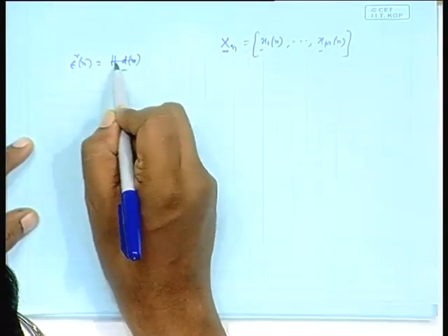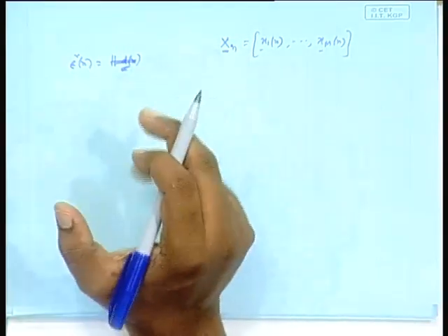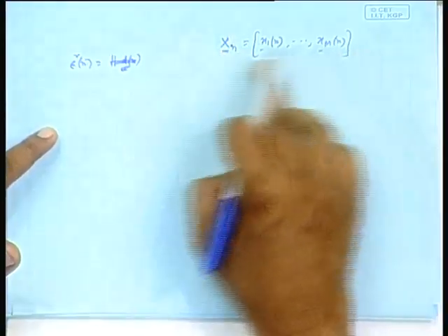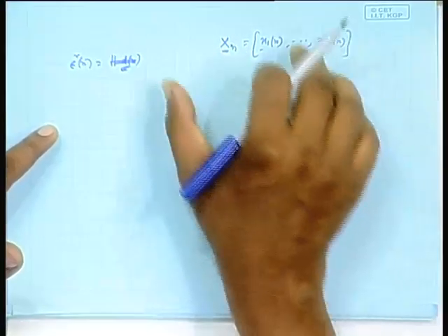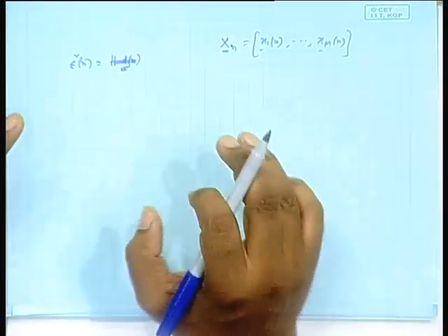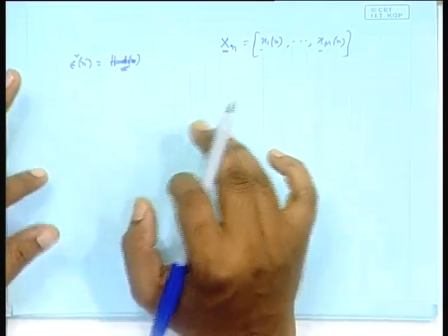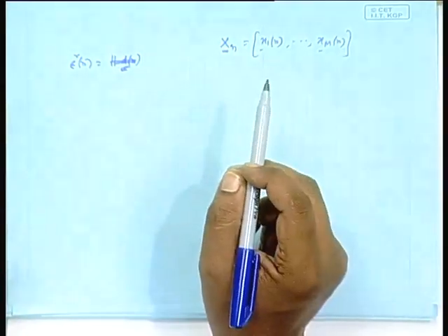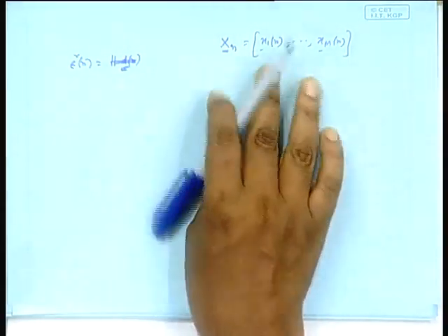This norm I converted into the conventional norm by writing out that delta part explicitly. Actually, you take d n minus x n into c n, that error vector, and take the norm square. In that norm square, your lambdas would come. You remember, norm square of any vector in my definition is that vector pre-multiplied by a diagonal matrix 1, lambda, lambda square, up to lambda to the power n.